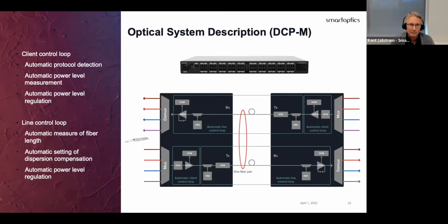We take this wavelength, we go into the mux. If we look at the bottom left part there with the blue wavelength, for example, we go into the mux with a specific wavelength. We multiplex that through what I call a standard multiplexer using a technology called AWG. We go through a block that we call an optical equalizer. That is effectively a component where we get access to each individual wavelength, so we can individually attenuate them to the appropriate level. Then we go through a booster amplifier.